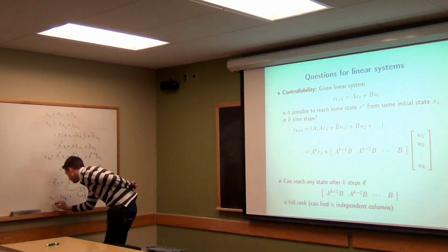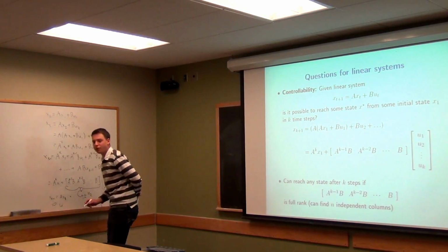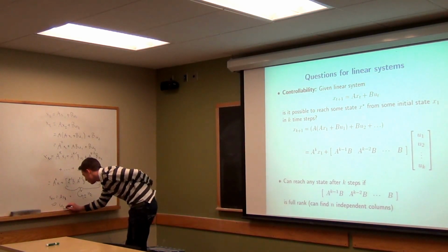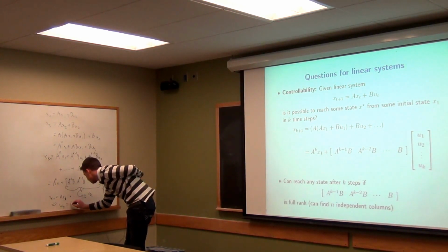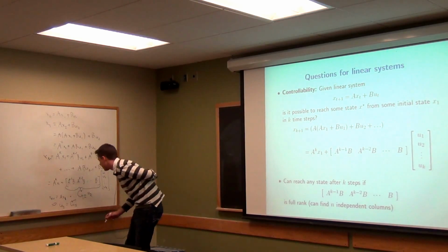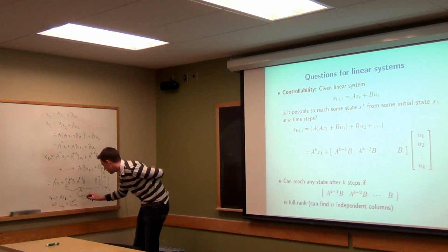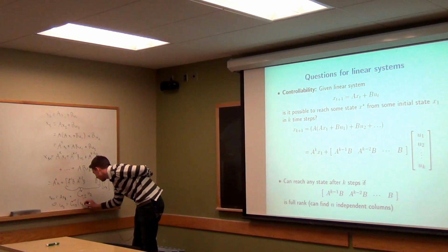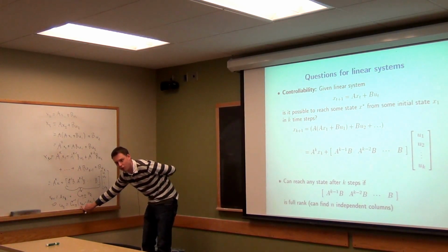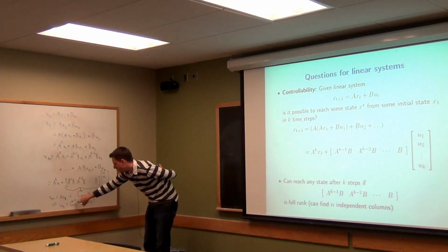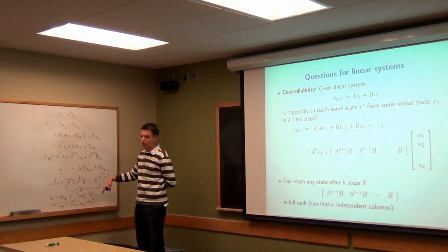So now we can say that u_I, sorry I'm running out of space here, the control we're going to apply at those 4 indices, is just going to be equal to script C, those 4 columns, inverse, times x_{k+1} minus A x_1. So again, we know what state we want to get to, we know our first state, and we can find a set of u's that will get us there by inverting the matrix.